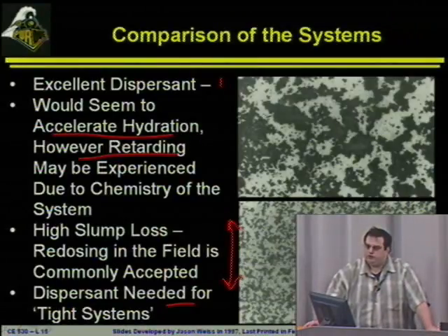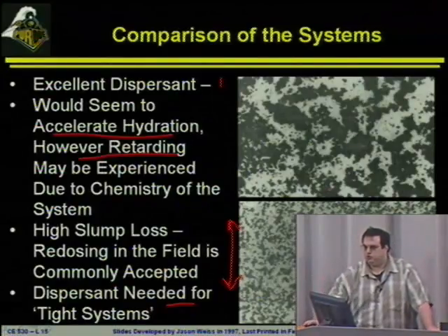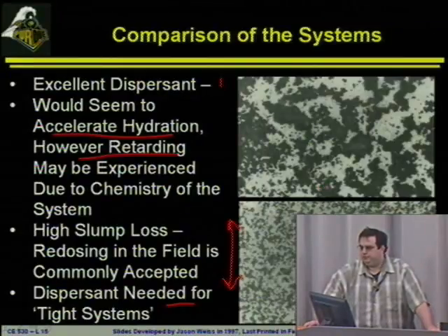One of the issues is if you've got a real dry fine aggregate, the dry fine aggregate is going to act like a sponge, and it's sucking up the admixture that you're spending money on to put into the system. So you'll see some of that absorbed. You'll also see some of the materials that get caught up in the hydrated products, and once that happens, then they won't be as effective. So that's sort of going back to the question that you had earlier on where they end up. Okay.